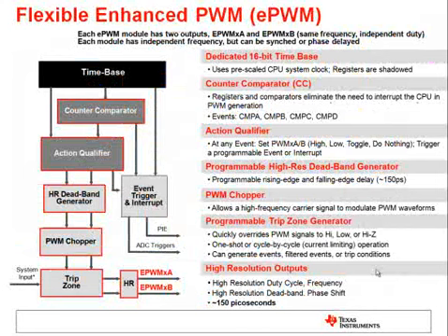The Enhanced Pulse Width Modulator peripheral is a key element in controlling many of the power electronic systems found in both commercial and industrial equipment. An effective PWM peripheral must be able to generate complex pulse width waveforms with minimal CPU overhead and intervention. It needs to be highly programmable and very flexible while being easy to understand and use. And that's exactly what C2000's PWMs were designed for.